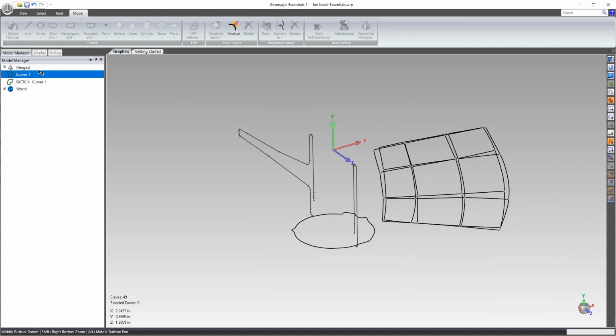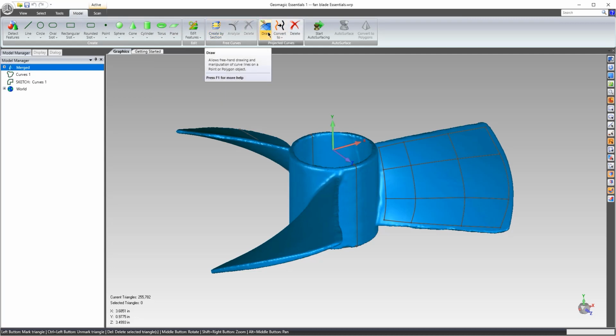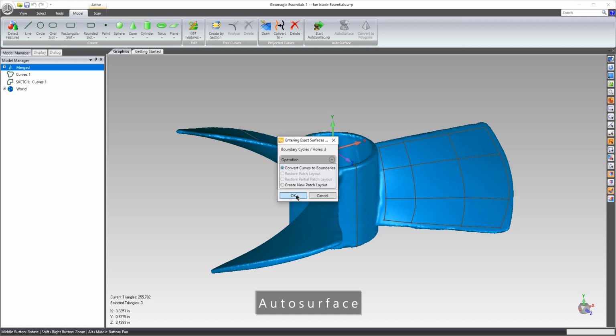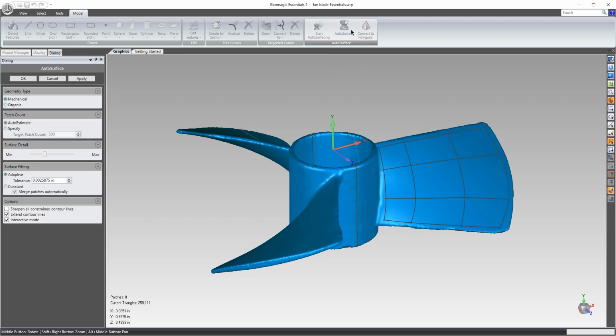And then the other thing that you can do with this, so there's three types of geometry that we can extract from the model. One of them is prismatic features, which we used for alignment in this instance. The second one is cross-section curves. The third, actually four types of geometry, is cross-section curves and splines on the mesh. I guess you could create curves, whether they're 3D or 2D, as one object. And then the other one is auto-surfacing the object. So auto surface will go ahead and wrap a surface around the outside of this object and create a CAD body that you can then export and send over to Solid Edge.